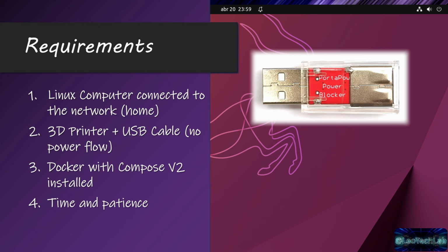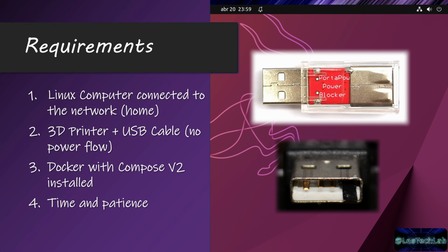Or you can take a little bit of isolation tape, so electrician tape, and cut just a little bit of it and cover the fourth pin on the right. When you're looking down in the front of the USB plug, the fourth pin on the right is the 5-volt pin. Okay, so if you cover that pin and let the other 3 pins go through, it will only allow data to pass. Okay, and that's what we want.